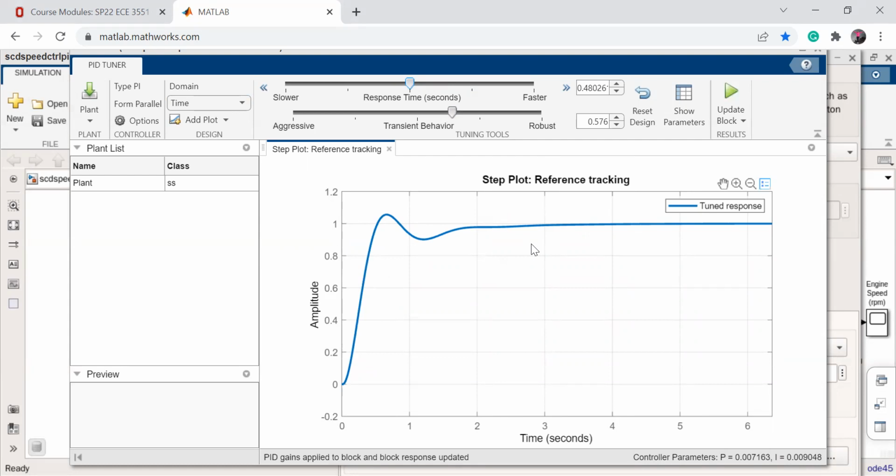Now, if you run the Simulink again, I forgot to run it before changing the controller. It was not stable. So when you're doing this at home, do that. And once you update this, the response of your closed loop system in Simulink will look exactly what you expect. It will get rid of all the noise, and then you're tracking your input signal.